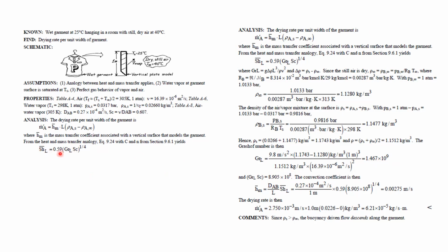So we will be determining the Nusselt number, and from that the heat transfer coefficient. Now the mass transfer coefficient we will be determining similarly, so that will be h_m. Here you can see the heat transfer coefficient h was Nu times k by L. Similarly, here it is D_AB by L times the Sherwood number. So that will be this value. Please note that this is meter per second. It's not velocity. It's that per unit length. It should have been meter square per second.